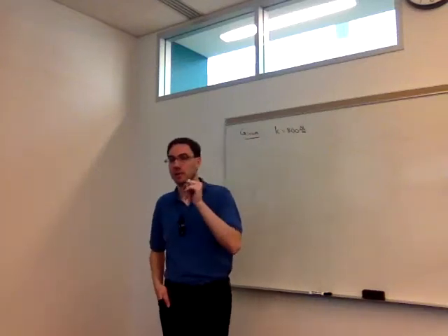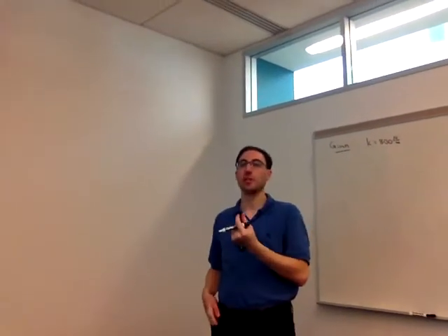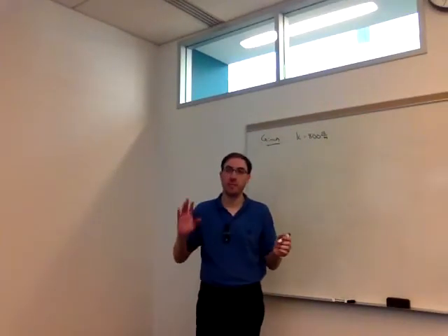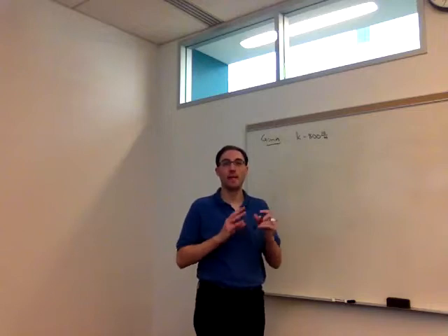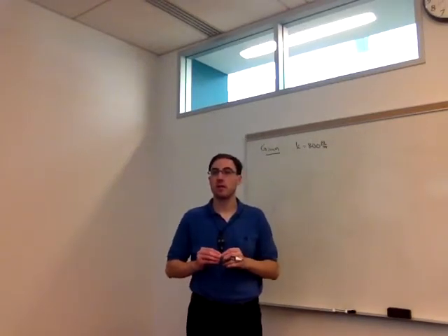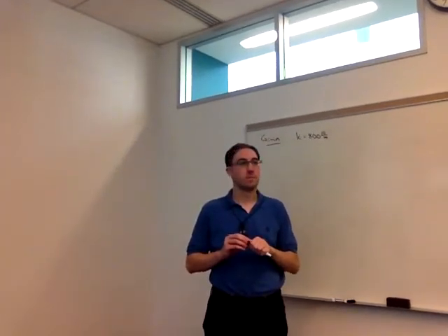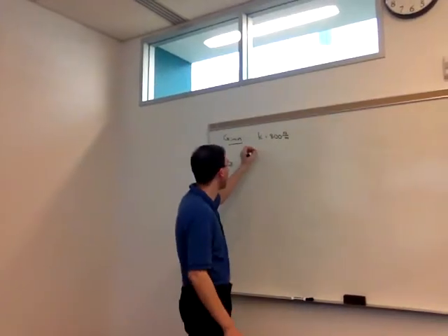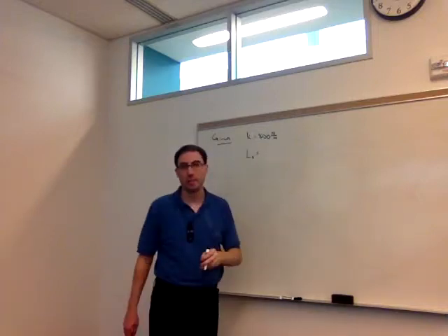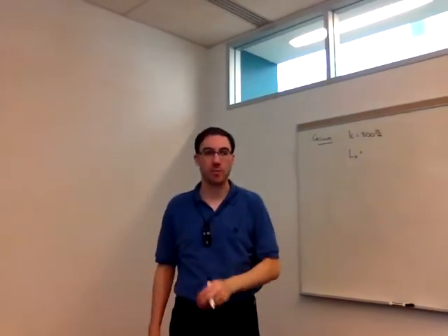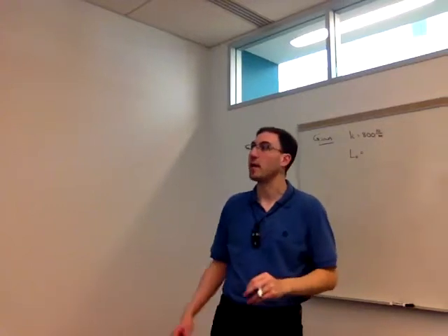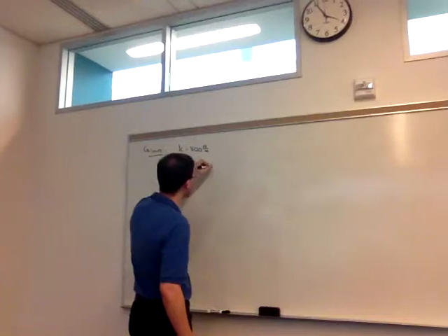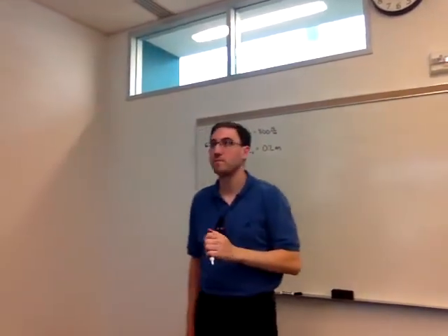The delta was the deformation or the change in length of the spring. So it can change depending on where you're looking, but based on the slides I presented, what meant unstretched length of spring? Just so that way if you look at Hooke's law, it works. So I used L naught to be the unstretched length of the spring. So if it's just on the table, not attached to anything, then the distance from end to end of the spring, I'm going to convert it to base units right away here, so 0.2 meters.